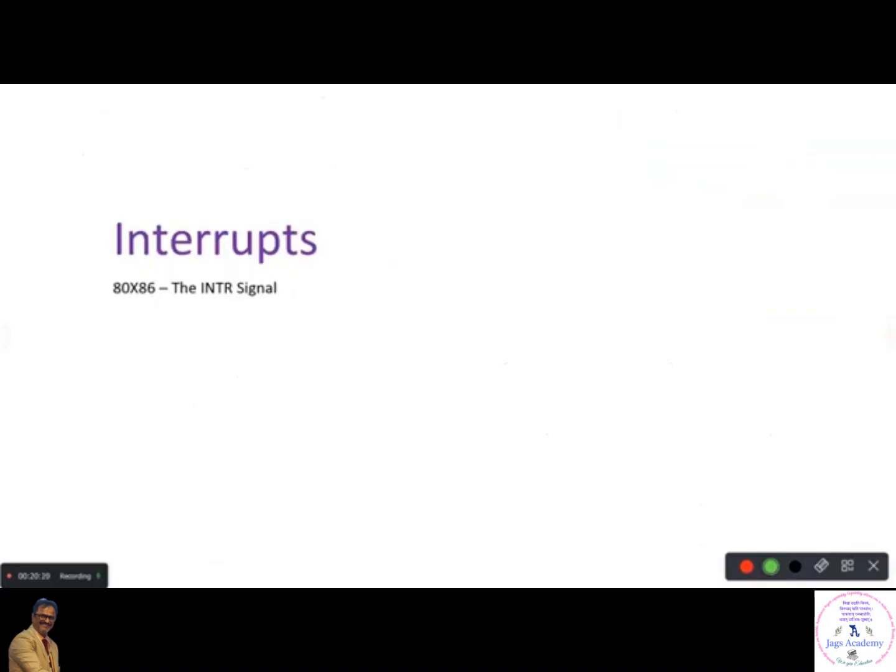So these are, as I told you, the top 5 interrupt numbers that are actually reserved for specific purposes, right? So now, how many interrupts are left for us? Out of 256, we saw only the top 5, top 6. What about the remaining? Have you checked in my previous slide that interrupts from 5 to 32 are reserved by Intel? I don't know why it is reserved. Now, above that, after 32, you can use interrupts for different purposes. Certain interrupts you have already used in the lab. What is that? 21 you have used.